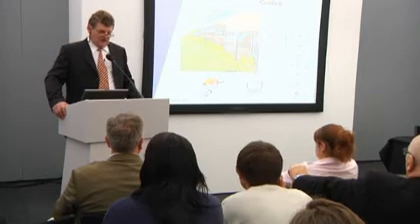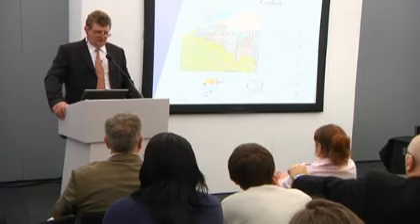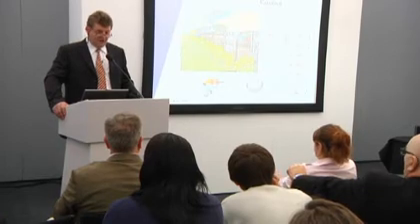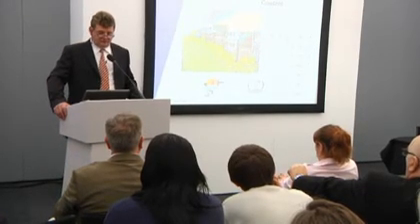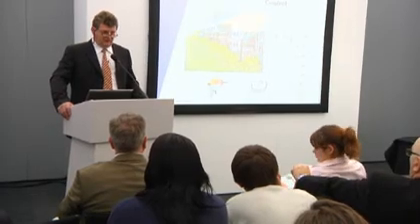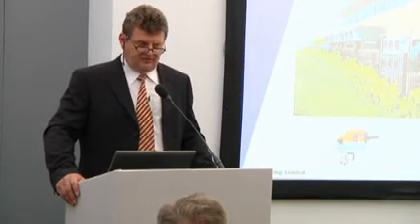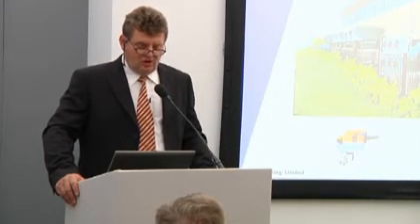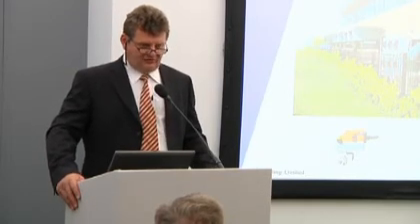How we control a computer room set is on two things: temperature and pressure. We monitor the pressure, in this case, of the raised floor, the underside of the raised floor, because we know if we're achieving, in this case, 20 pascal of pressure in that underfloor, we're getting the right flow. And a key part of commissioning is to understand how your raised floors are working and how your total flow rate of the server room is operating, what is required, and give it the right amount. Also, it gives us a control measure.